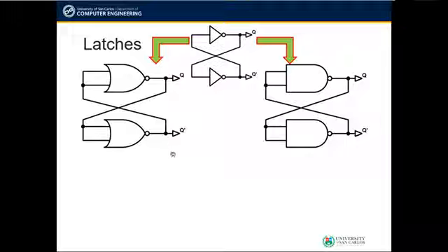Now, what if we modify these circuits a bit so that we can introduce inputs to them to vary their outputs? We can do that by disconnecting the shorted inputs to the NOR and NAND gates. The circuit will now become like this.